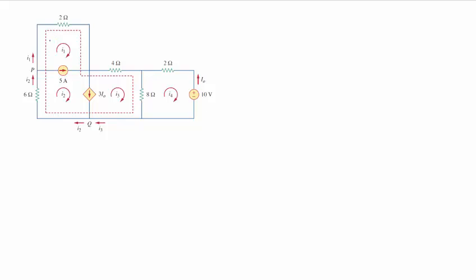And so when I write the equations, I'm going to write an equation for one big loop here. So I can go ahead and do that. And so remember, I1 is in this component, I3 is in this component, I4 is here. I have something going on here. So I'm back in this loop, so I have an I3, and I'm back in this loop, so I have an I2. And that's the way you would write the equation.